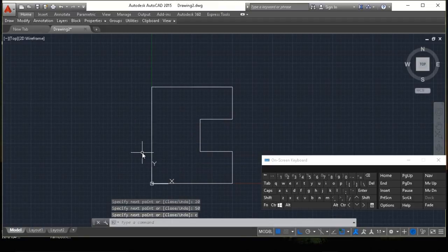Now I am going to explain how to convert it into a 3D diagram. Look closer. It is a very simple method to create a 3D diagram easily. You have to follow two commands, the region command and the extrude command. The region command helps you rejoin all the lines.